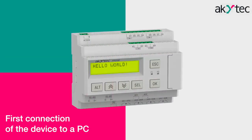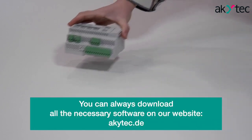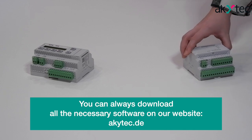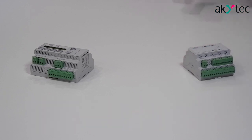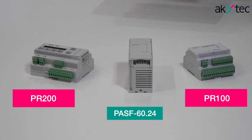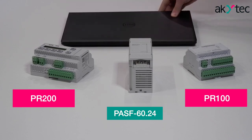Hello everyone! Today we will look at the process of connecting our mini PLCs to a computer and downloading the simplest project directly to the device. For connection, we will need a PC and a cable. In the case of PR200, this is a mini USB cable included in the package.